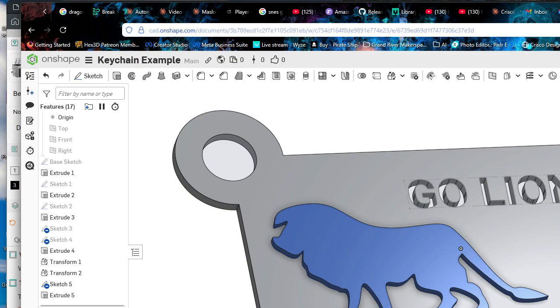Try to select the sketch entities now. So like draw a box around the whole thing, around everything. See if you can grab any of it. Okay, now choose this point over here as your scale point. Click on that little box there. See how it says point? So you have to highlight it blue. Now select the point you want to scale away from. Okay, so now choose like 0.5 there. You should see it reduce. If it doesn't, then this trick didn't play.